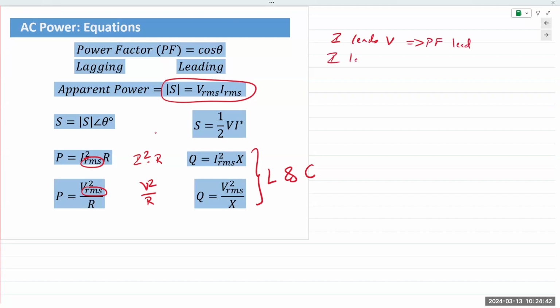If current I lags the voltage, then we say power factor is lagging. This comes from the fact that for an inductor, the voltage always leads, and for a capacitor, the current always leads. If you need help, we can turn to Eli Manning and use this mnemonic, ELI the ICE man. It's not really named after Eli Manning.